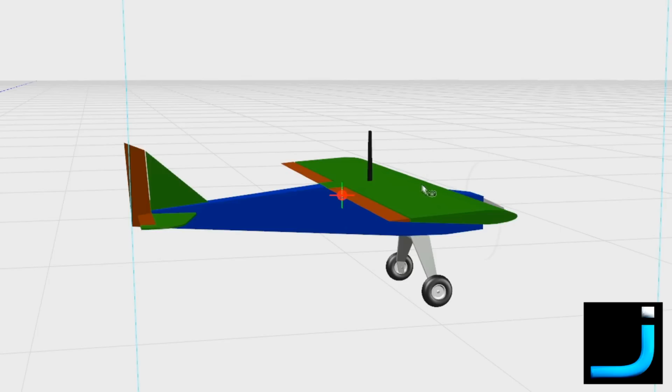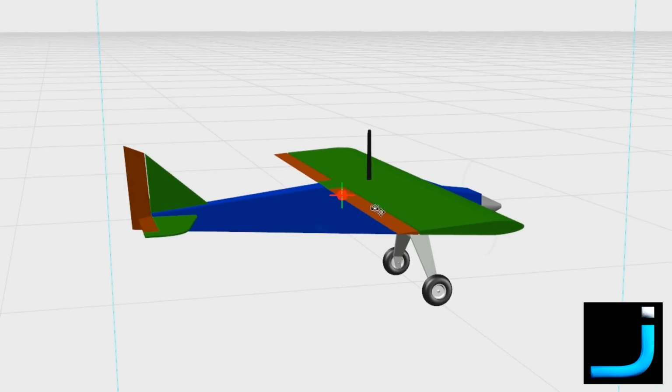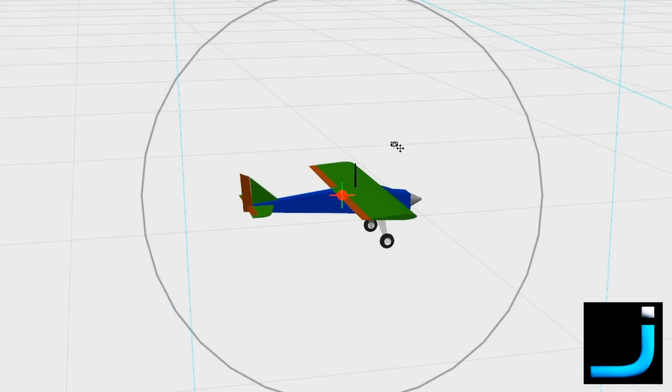So let's deal with the gain first. A lot of people think the gain represents some sort of strength or the sensitivity of the antenna. What it really is, is it determines the pattern. And you have high gain and low gain antennas. Now, a 2 decibel Omni antenna like this would be a low gain antenna. The benefit with low gain is the pattern goes all the way around it. The field of view, if you like, is extremely wide, and with an omnidirectional, it's in all directions around it.